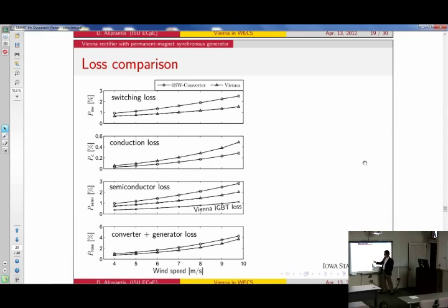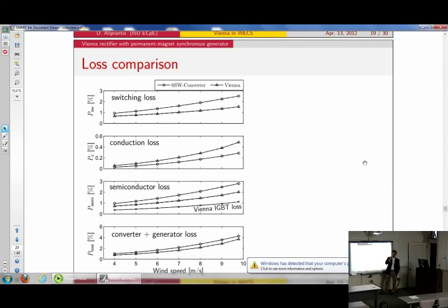However, the other advantage of this is, going back again, the reduced voltage stress. You get half the DC link stress across the semiconductors. We think that this will lead to increased reliability of the system. You don't stress them to, let's say, 1,000 volts. You only stress them to 500 volts. And we have seen a few papers that hint to that effect, that the thermal stress on the device is less, which leads to increased lifetime and increased reliability as a consequence, which might be important in a wind turbine application.